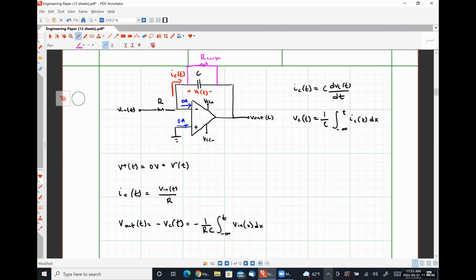But for now, just understand that effectively this part without the pink bit functions as an integrator, but it does depend on whatever the initial voltage drop across the capacitor is, which, if you're trying to design a circuit or anything like that, just force it to be 0 in your simulation.